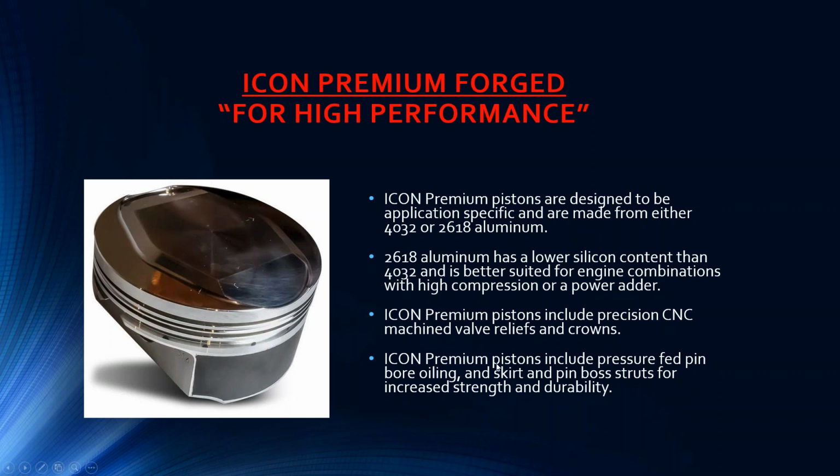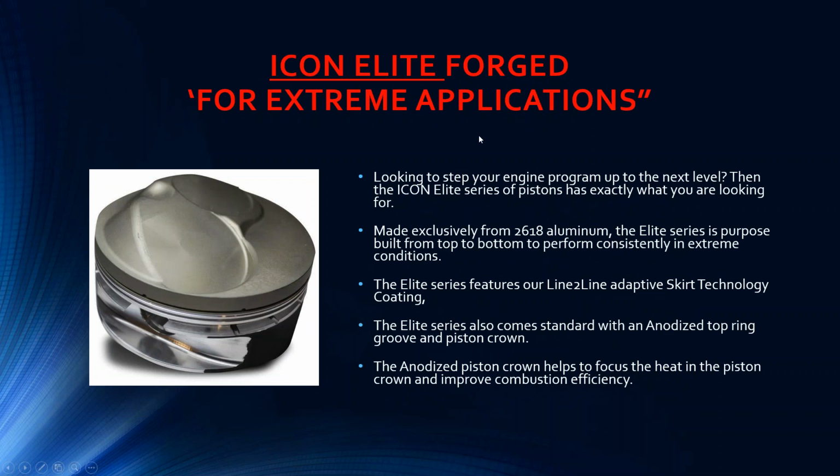And also in our Icon Premium, we have pressure-fed pin bore oiling and skirt and pin boss struts for additional strength and durability. We also have our Elite Icon, and this includes our line-to-line abradable adaptive skirt technology that you see here, and also includes our anodized top.